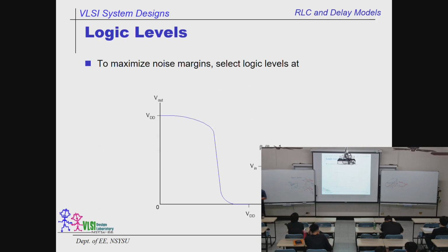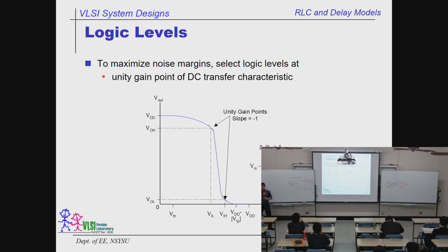So how do we define the logic levels? It's over here. It's quite easy. This is the inverter, and you have a size ratio beta P over beta N. Not hard. We take a derivative, because unlike those square waves in the textbook, the real inverter timing response is a continuous signal. There is no discontinuity.